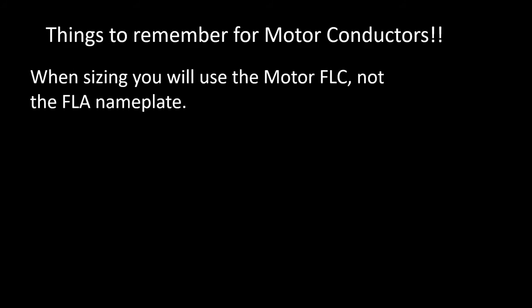So some things that we have to remember is that when we're sizing motor conductors, we're actually going to use the motor FLC and not the FLA nameplate. Now, if they have the FLC printed on the nameplate, then you can use it. But if it's just some amperage stamped on the nameplate, or if it says FLA, then you're not going to be using it. You're actually going to be using the FLC.